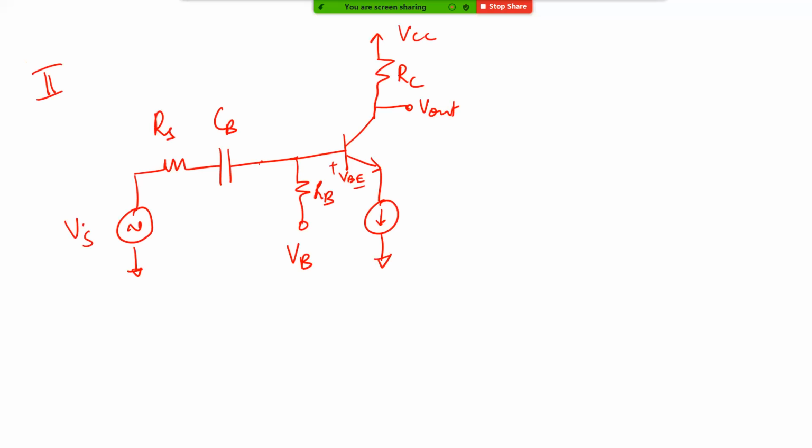Now the third way, DC current of 50 by beta plus 1, right? Forced in the base current. Base current 50 by beta plus 1 will be forced, right? Yes. So the current that is flowing here will be 50 micro by beta plus 1 plus small IB.